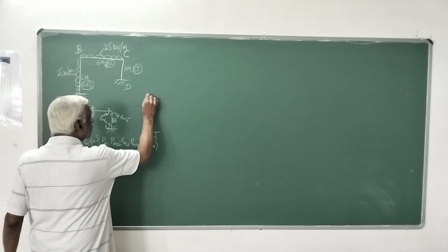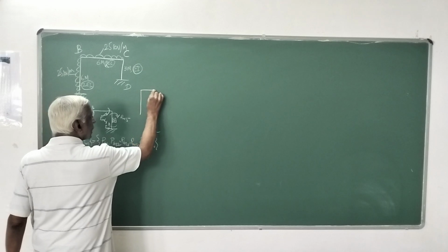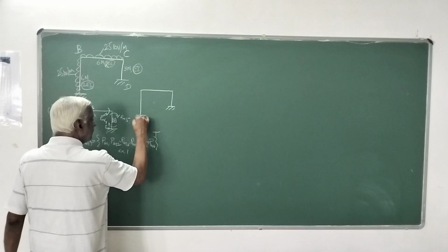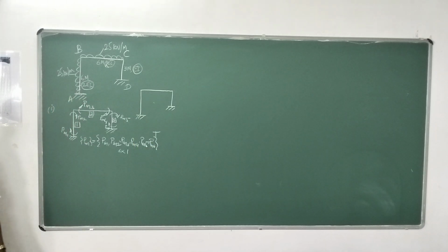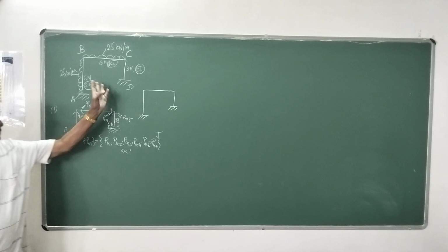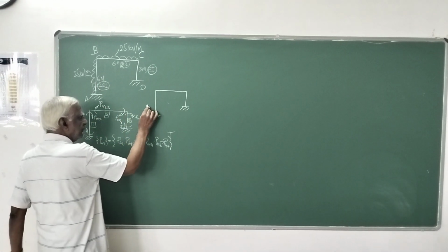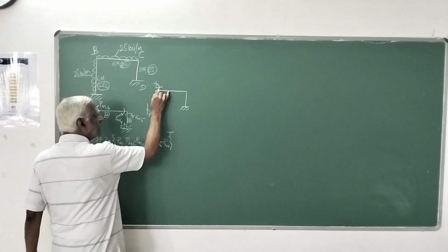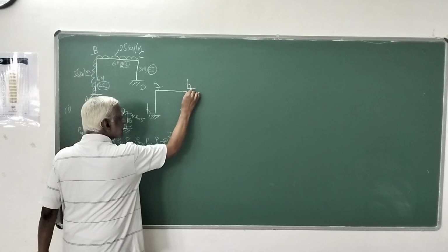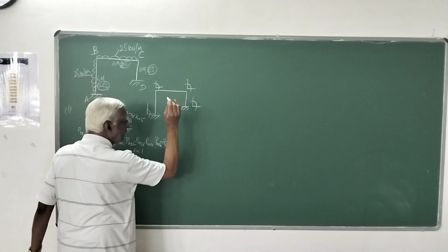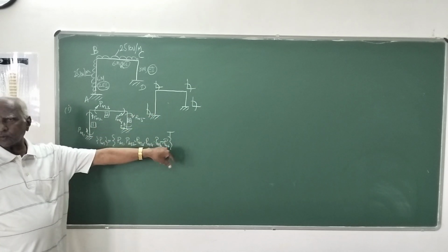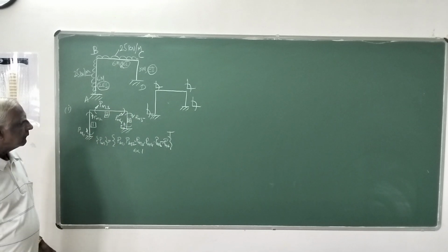And the global coordinates correspond to the displacements which we have to determine in global coordinates or system coordinates. Actually, in plane frames we have at each node 3 types of displacements: horizontal and vertical, that is 2 translations, and a rotation about an axis normal to the plane.